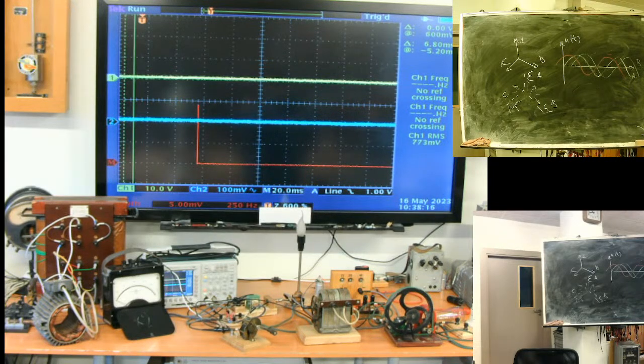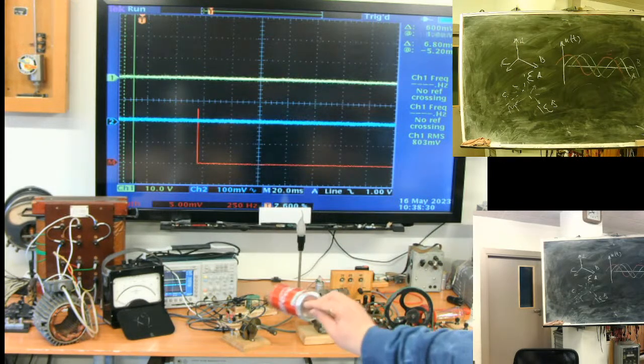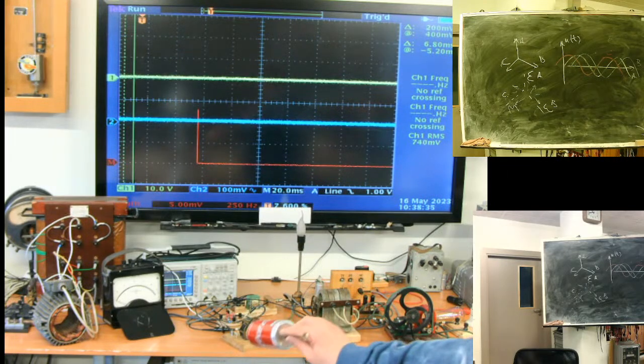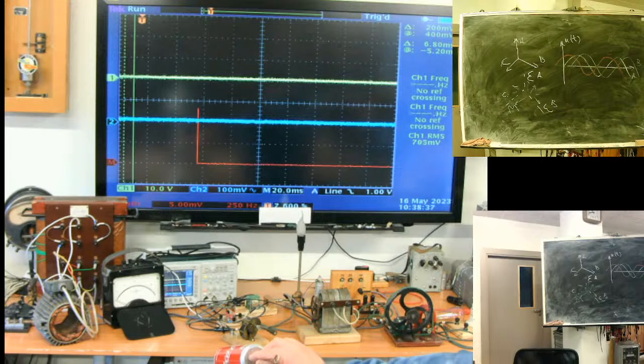All this surface is conductive. When current flows, a magnetic field arises. And the magnetic field from the induced current comes in mutual operation with the rotating field of the stator coils. That means what we will see? Moment, mechanical torque. And mechanical torque rotates.